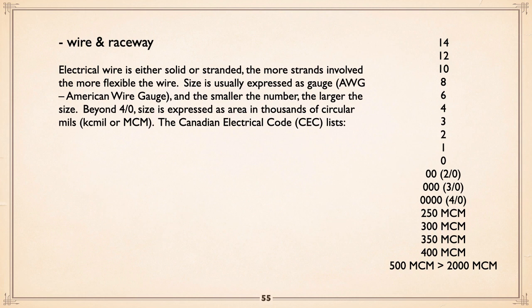In a locomotive, the motors are down where the wheels are, and the connection to where the power is being provided within the chassis of the locomotive has to be flexible. So they have very flexible cord, and it has conductors like you wouldn't believe, little tiny ones, relatively small, but a whole slug of them. Therefore, it's very flexible. That wire can be used and is approved for ordinary wiring purposes.